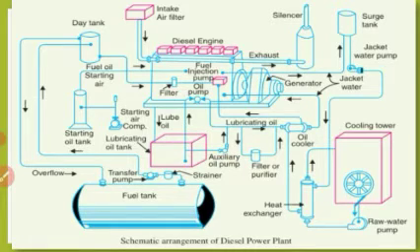I repeat, reciprocating air motors means they pass very high pressure air into the cylinders. So it starts rotating, to turn over the engine shaft. Once it starts, the fuel is admitted to the remaining cylinders, which makes the engine start under its own power. This is the method.